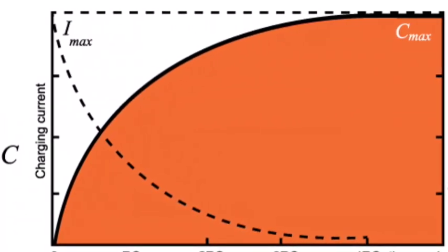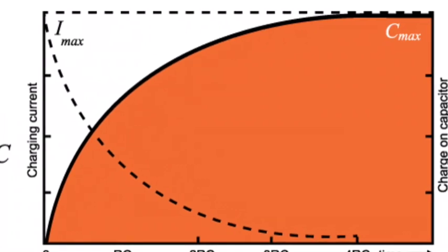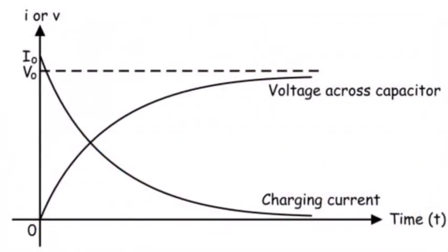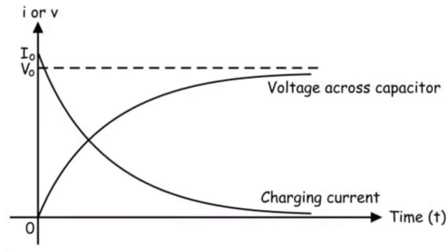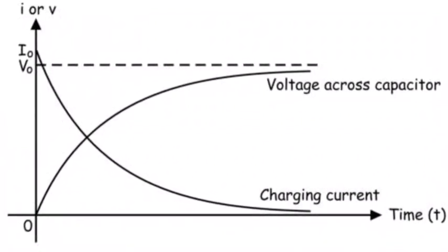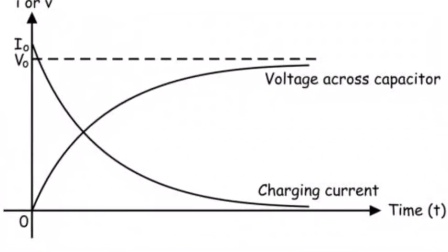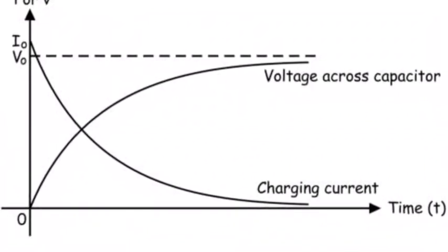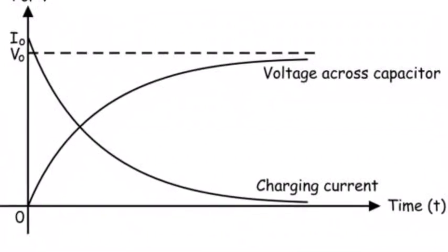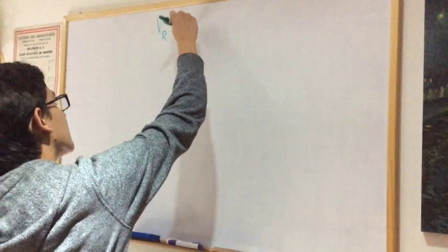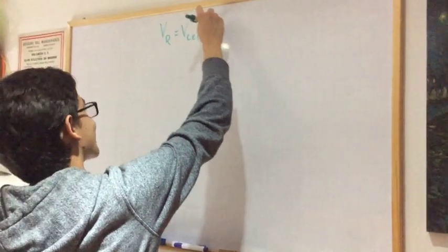When charging a capacitor, if there is no resistance, it charges instantaneously. Introducing a resistor will cause a measurable time delay, as the electrons from one plate pass to the other. Likewise, the voltage between the capacitor and the resistor is exchanged exponentially, as the capacitor begins without voltage and the resistor with all of the voltage. Therefore, by derivation, we could obtain the value of the voltage as shown.